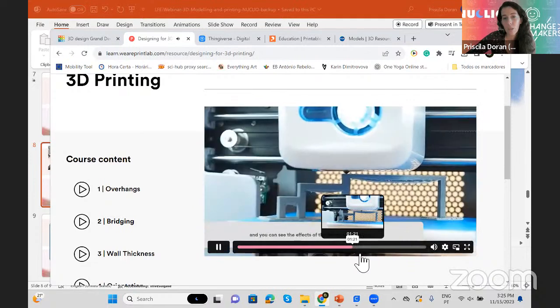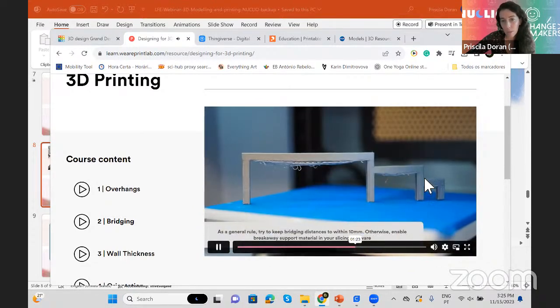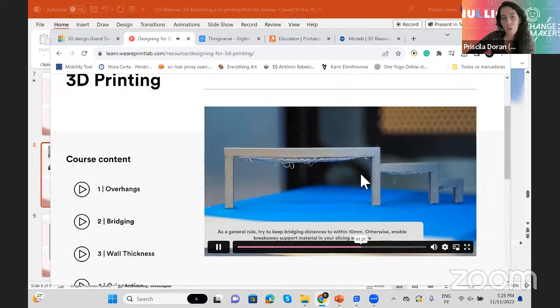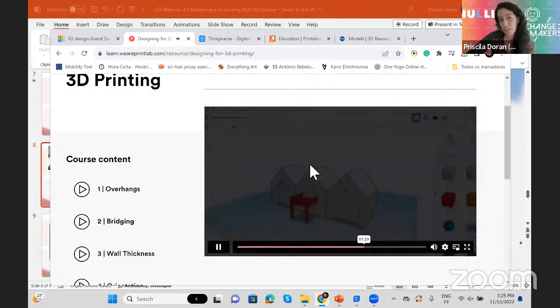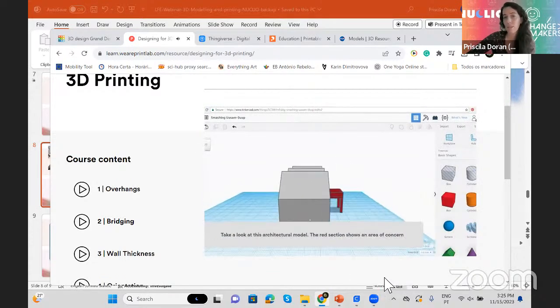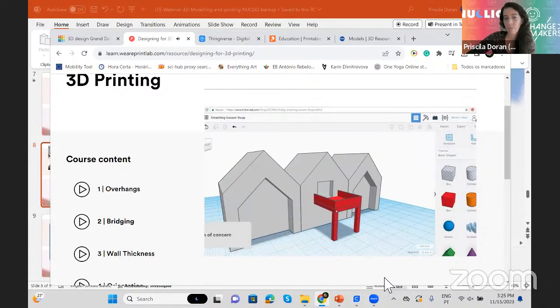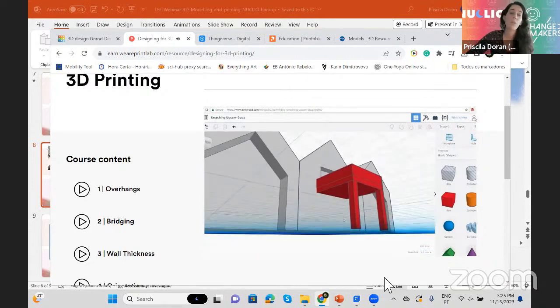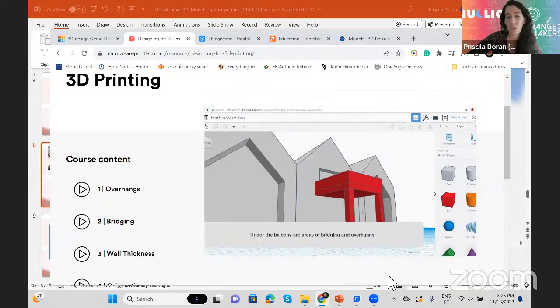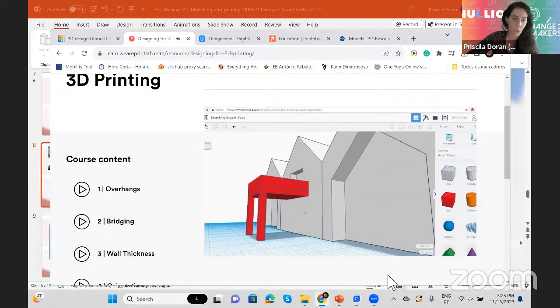And the final result is that the small one did kind of okay, the medium one, not so good, and then the other one is completely spoiled. And this is important when you're making designs that use this kind of bridges. You can obviously solve this with supports that are created automatically by the printing programs, and which I will show you in a bit.